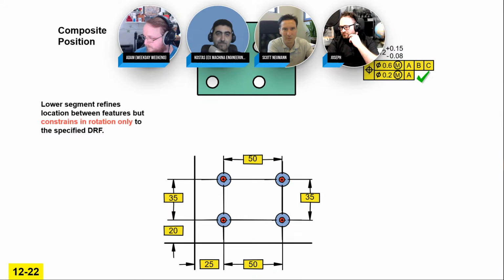Yeah, look it up. There's symbols here. Look it up in the book. Position tolerance. There's some great examples, and cylindrical tolerance zones. Once you understand it, you're like, why would you ever go back to plus or minus? It really is that way. Like, why would you ever do it the other way then? For a better system.